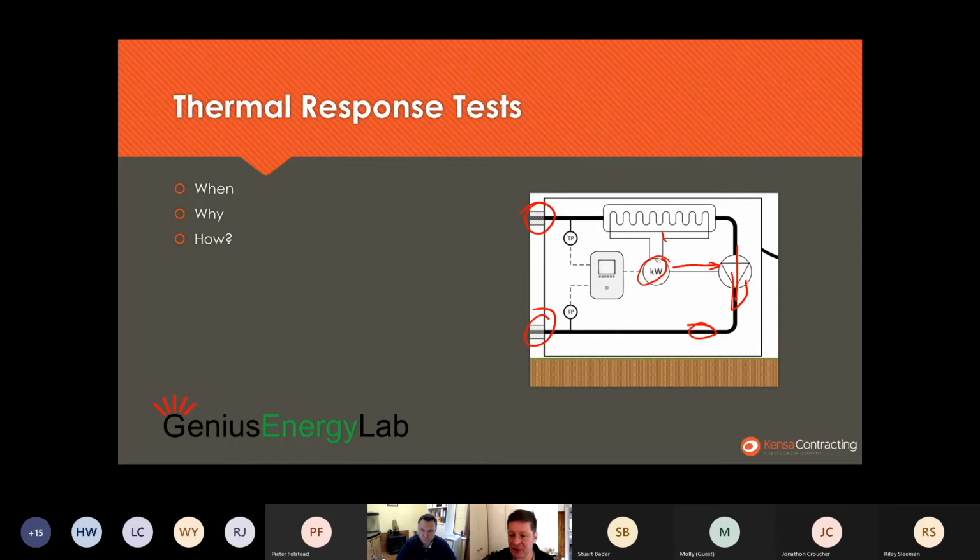Now, one of the reasons we measure it electrically rather than trying to do some kind of heat metering on it is that actually measuring electrical consumption is a very accurate and very easy process. So we simply squirt the electrical energy output into a data recorder, and all the rest we have to measure is the temperature coming back from the bore field and the temperature going out to the bore field. And again, you can measure temperature in a fluid very accurately. Notice we're not measuring the flow rate because that is a much less accurate process. So this test processing that we do is designed so we don't have to measure flow rate.